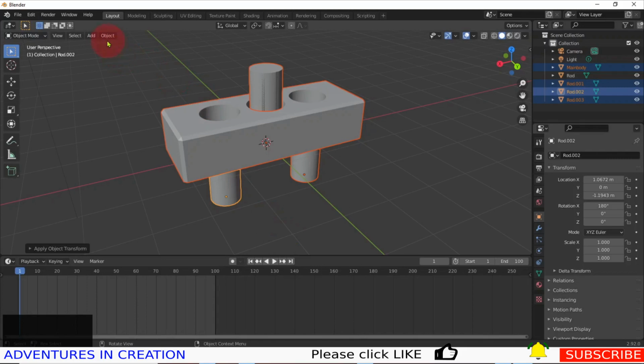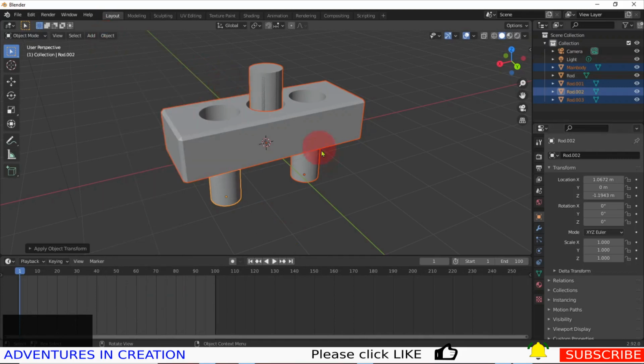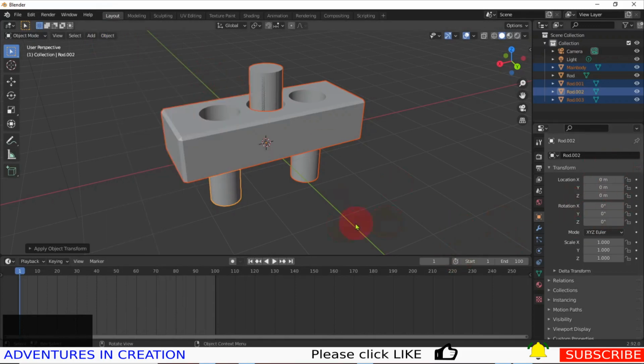And I can say Object, Apply, Rotation. So now my rotation is 0. And then I'm going to say Object, Apply, Location. And all my locations are 0. The reason I've done that is just to make everything simple. It's all zeros instead of being all those odd numbers that were on there.